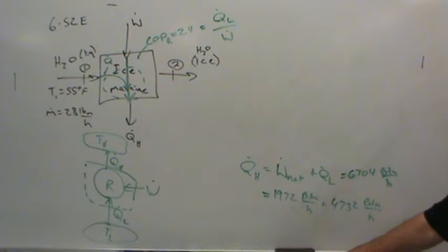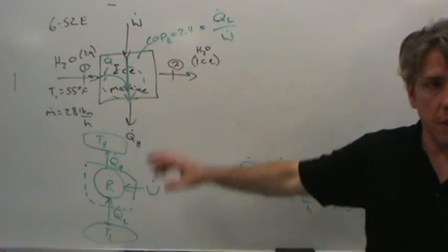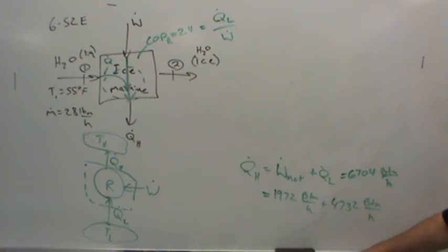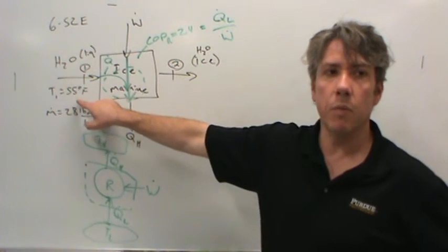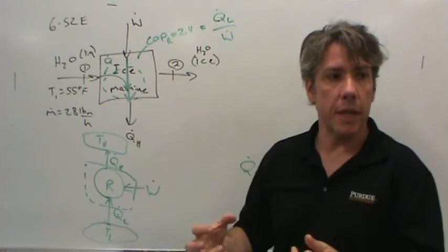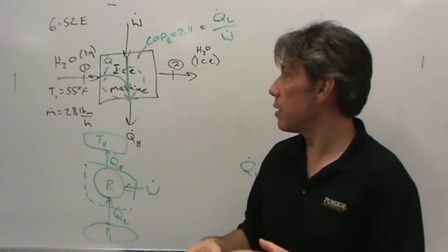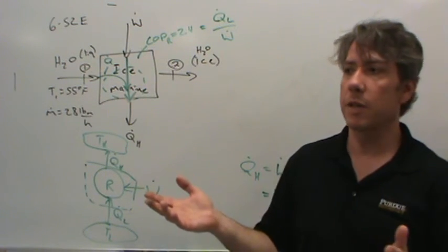So anyway, what I was going to mention is, notice this is about half of a ton, right? So this ice machine is accounting for about a half a ton of refrigerator, or heat pump usage, essentially. Okay? Now this might give you an idea. Well, wait a second. That's pretty cheap. So couldn't I bring in water from the tap, suck out all the energy from it that I could, figure out a way then to take that ice and toss it outside and heat my home in the wintertime?